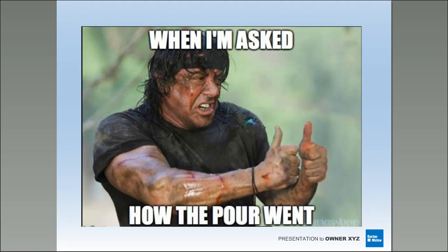But from everything I've heard, yes, I'd be concerned with lightweight. Lightweight aggregate is very porous and very soft, so your approach should go that way with the polishing. If I were going to polish lightweight, I would definitely do a mock-up, and I would mad scientist that thing to death on how I want to cut it to be most productive and err to the side of caution when cutting. Just remember, lightweight aggregate, depending on what you're using, is very porous, very soft. All right, I hope that helps.